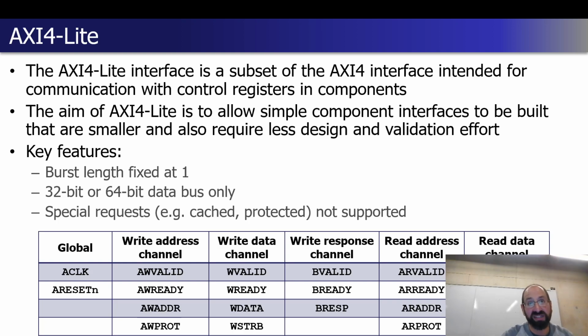It is the same set of signals effectively. It's kind of pin compatible, but the assumptions you can make make it a lot easier to write that state machine, to create that IP core. You're only going to read or write one single value at a time. It's fewer handshakes, fewer other edge cases you have to deal with in AXI-Lite.